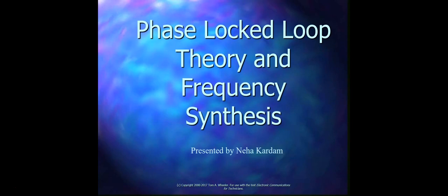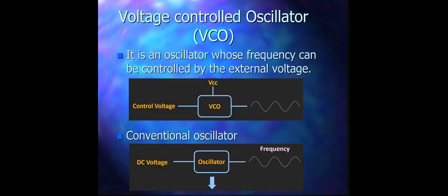In this lecture, we will learn about phase-locked loop theory and frequency synthesis. Let's first learn about a voltage-controlled oscillator. This voltage-controlled oscillator is part of a phase-locked loop, and it is an oscillator whose frequency can be controlled by an external voltage.